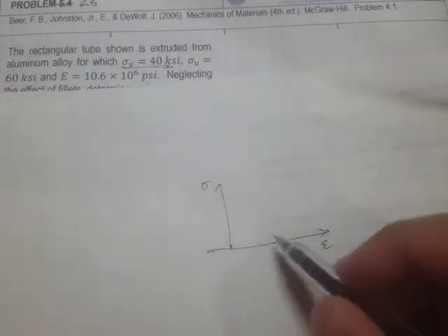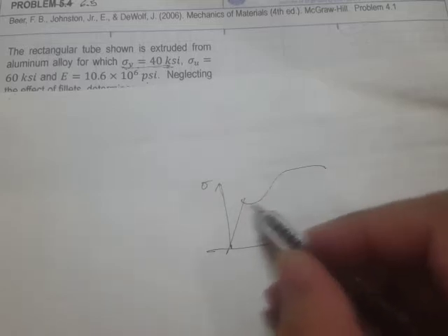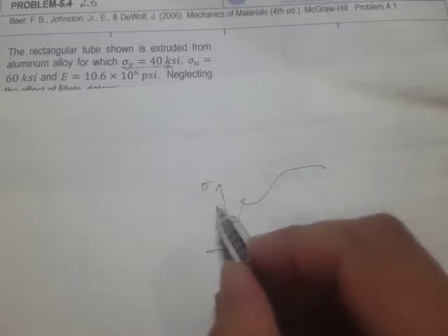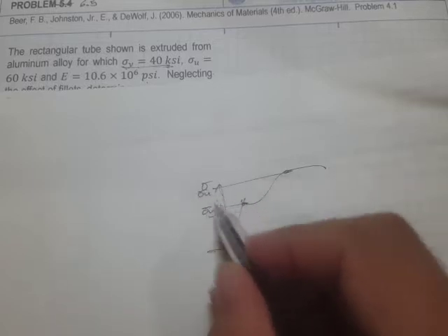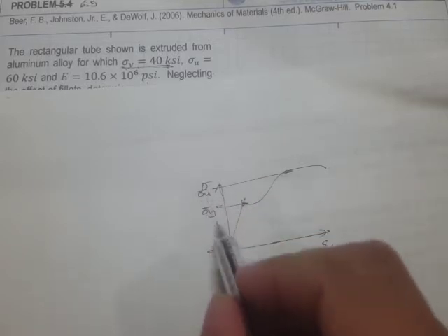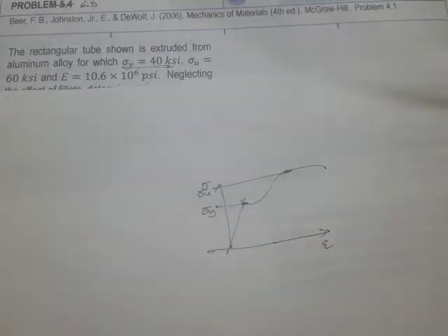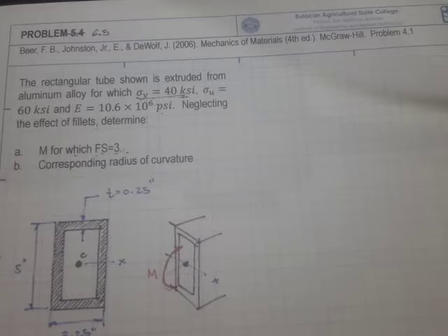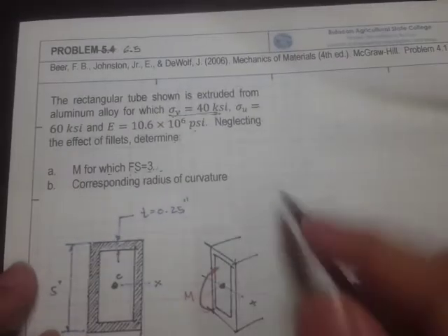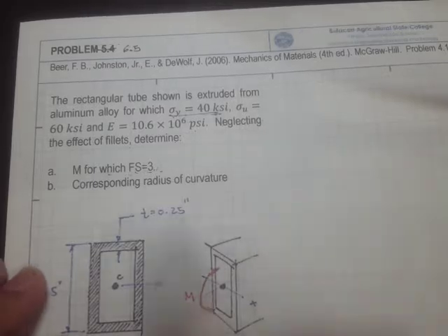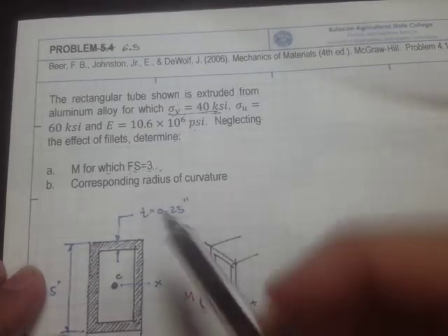And recall that in the stress strain diagram for a tensile test for steel, it looks something like this. And right here, this is the yield strength, sigma sub y, and here is the ultimate tensile strength, denoted as sigma sub u. Although this is for steel, the yield strength and the ultimate strength also exist in some other ductile materials.